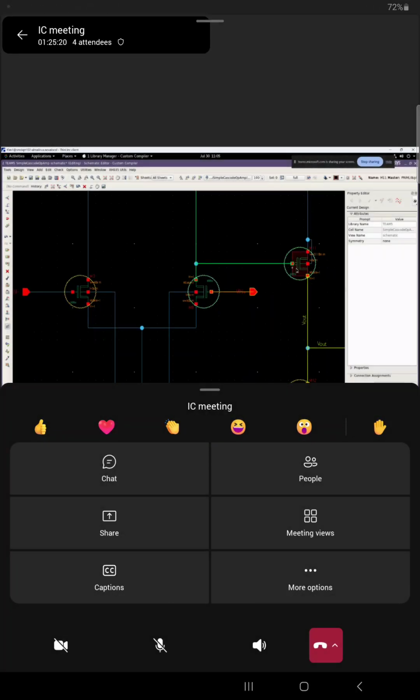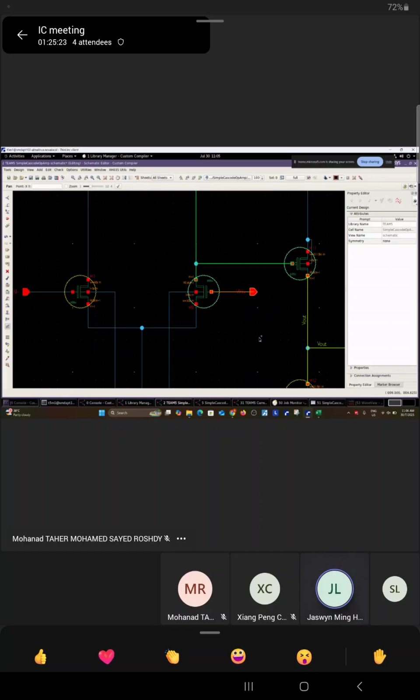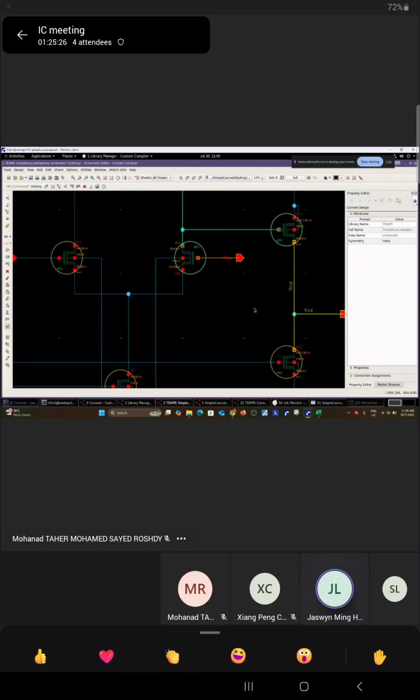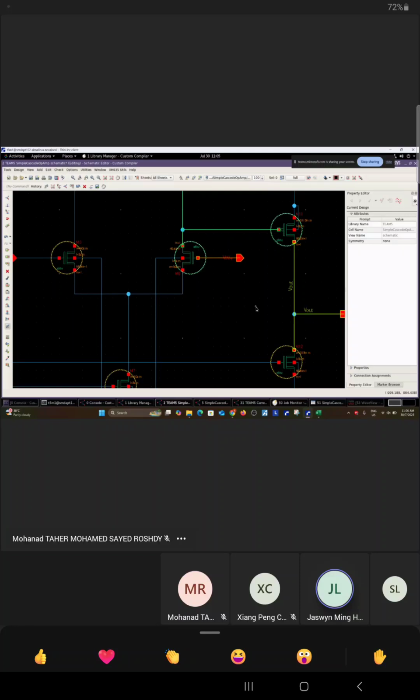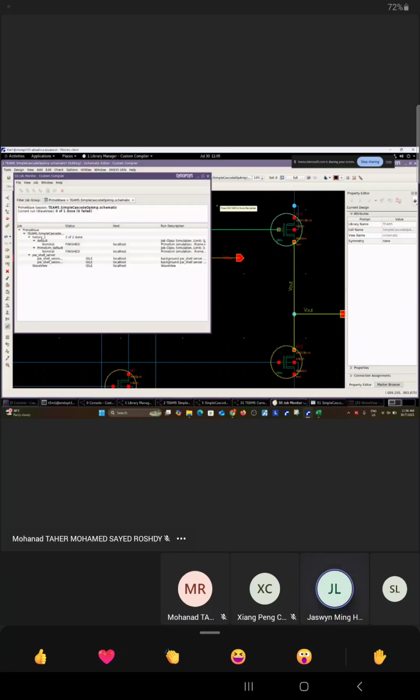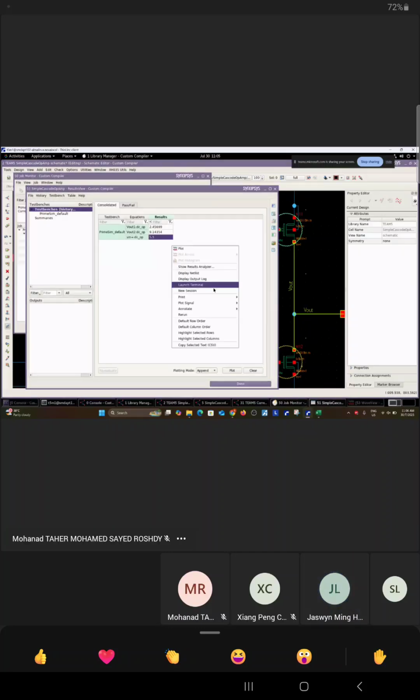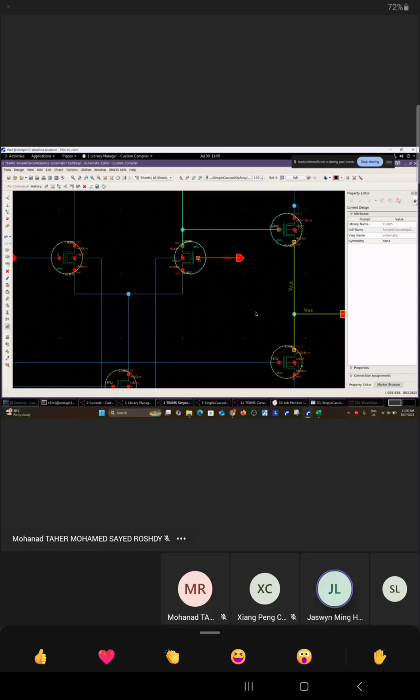We go ahead and talk about this. Just now when we had VD at 0, you get this one to be triode, this one to be saturation. And now when you go to VD of 0.5, you get this to be triode, this one to be saturation, right? This means that your V out now hits a maximum cap. You can try to annotate the voltage here. It will show you. Now it's 9 point something, already hit the cap. It goes either to zero or so high, like a square wave. I think this is part of the problem.